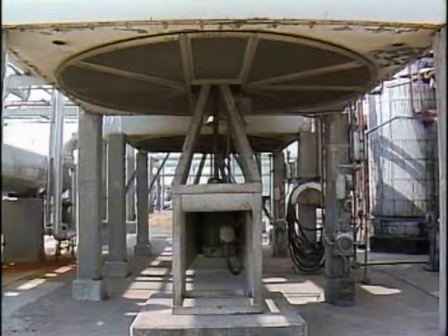The cooler consists of a series of tubes, each of which has thin metal fins. The heat exchanger also has a fan. During operation, the fluid being cooled passes through the tubes. The fluid transfers heat to the tubes by conduction and convection. Some of this heat is then transferred through the tubes and into the fins by conduction. From there, heat in the tubes and the fins is transferred by conduction and convection to the surrounding air.